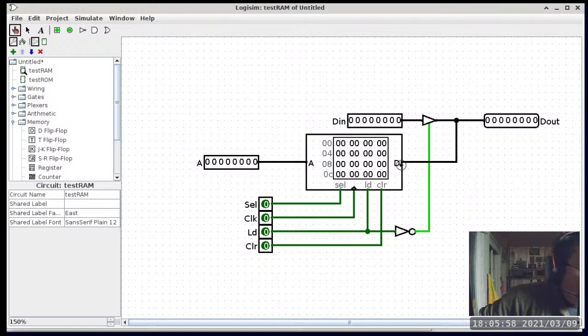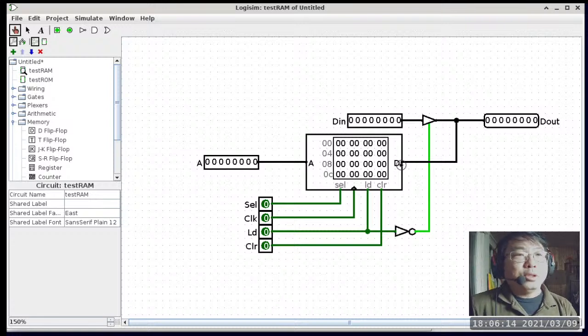ROM stores code that never gets changed. That is correct. And I'm just reading the text channel, and I'm going back up. So would a use of ROM be maybe like an instruction set? Yes. So it depends on what you call an instruction set, Anne-Marie. Because in the toy processor, the only purpose of the ROM is to store the microcode. Okay, so it's a little bit different compared to an actual conventional computer, where you would have some ROM to store the bootstrap code for that computer.